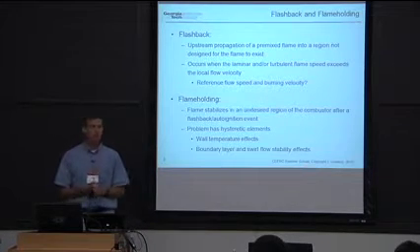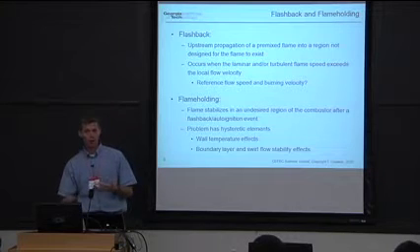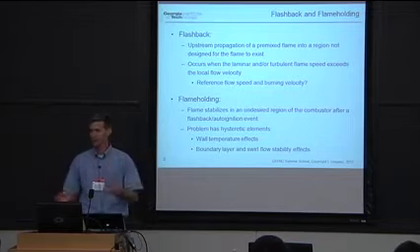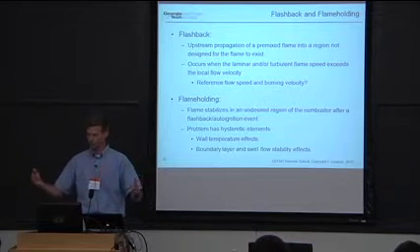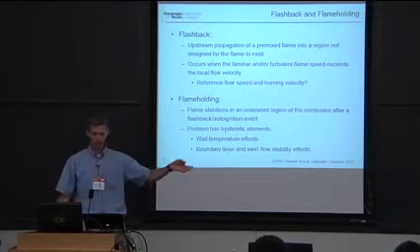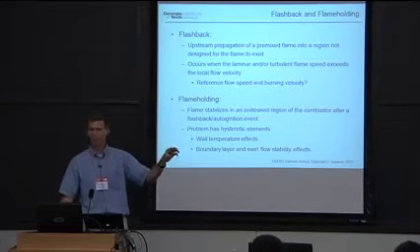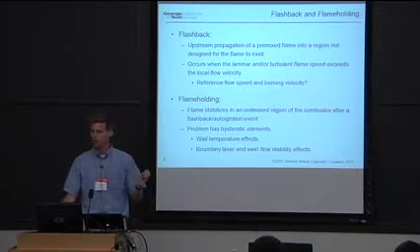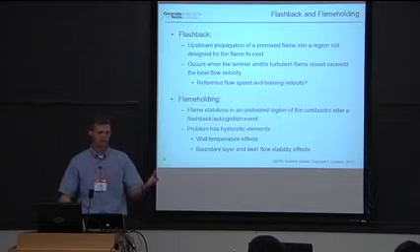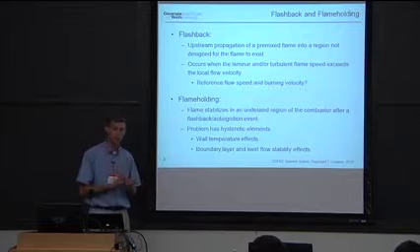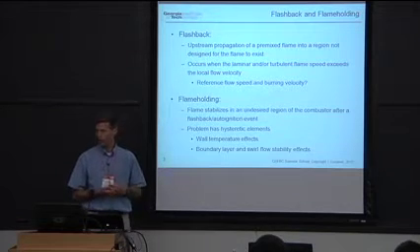Because a nozzle may be resistant to flashback for the most part, but there are always hiccups, right? I've been talking about grid transients and all this crazy stuff. What if, for some crazy reason, or a condensed droplet of propane goes blasting through, a flame gets introduced into the nozzle, and the nozzle can't spit it back out? That's the issue. So flame holding is a more severe and rigorous test of the nozzle.